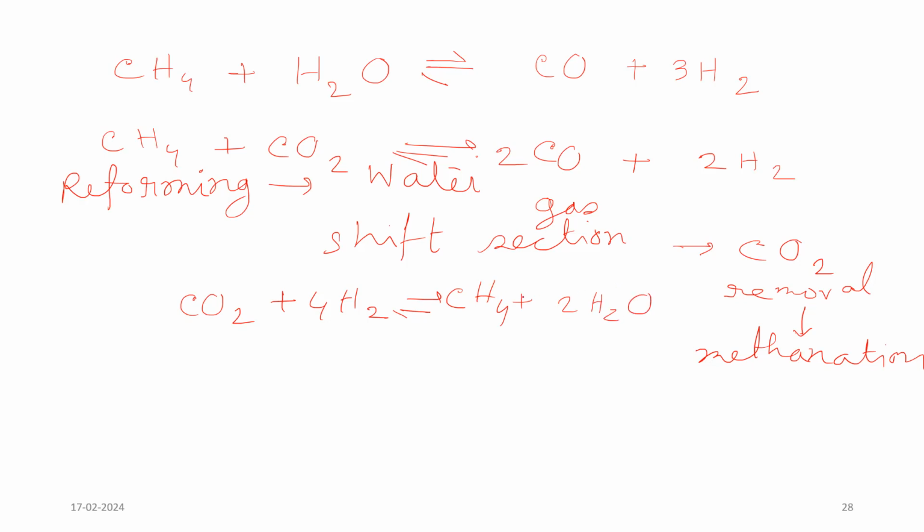You will see the stoichiometric balance; I am not correcting it. I am just saying this is the equation of the methanation reaction. So first CO is converted to CO2 in the water gas shift reaction, then CO2 reacts with hydrogen and produces methane, that is called the methanation reaction.